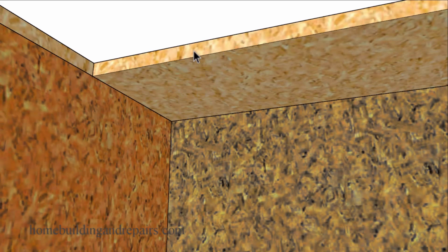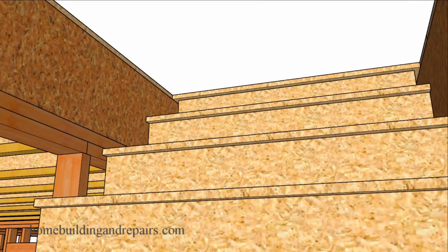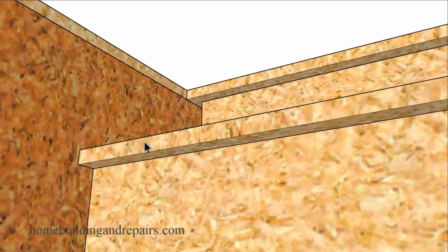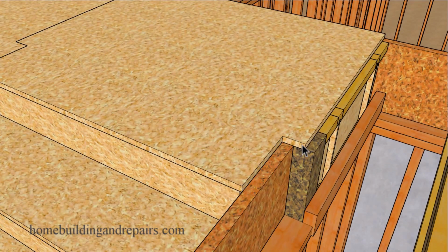And let's not forget that in this example here, we are going to need an overhang. We're going to need to extend the floor sheathing so that our tread overhang will work. We are going to have a 1-inch nosing or a 1-inch overhang for our stair treads. And that means we're going to need it up here also. And of course, you will need to switch directions here.